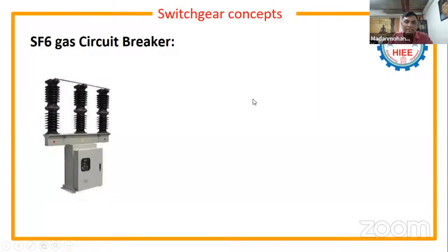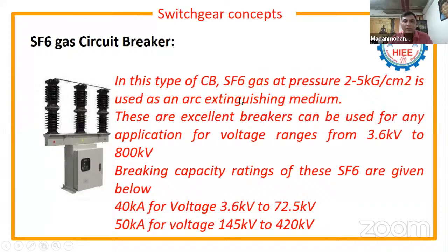And for transmission voltage levels like 132 kV and above, the fault level for 3.3 kV to 66 kV, we go with 40 kA. These fault levels depend on the manufacturer recommendations and your requirement, guys. Generally, SF6 circuit breakers are used in the system for 132 kV and above. So for 132 kV, 220 kV, all these applications, we prefer to go with the SF6 circuit breaker.